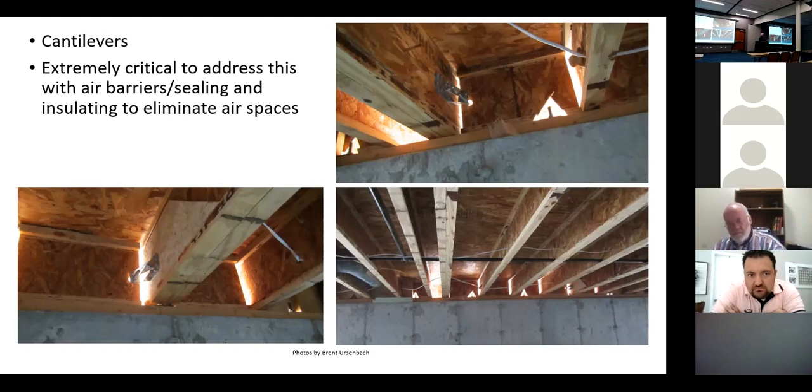When we get to this afternoon and we're talking about rim joists, the code has a table in it, the insulation and air barrier inspection list. And it says that our rim joist insulation has to be enclosed on all 6 sides. It has to have the air barriers. How do you insulate that and have 6-sided insulation? Closed cell spray foam. I don't know of any other way to do it. Do you? You take a piece of bat and shove it up in there.